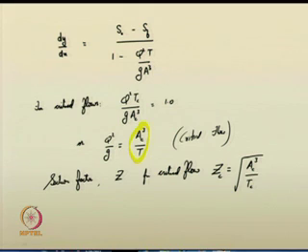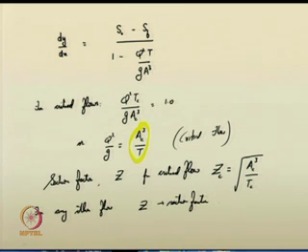So, for any other flow, not only critical flow, you can define the section factor. This is nothing but equal to the cube of area by top width, the whole thing you have to square root it. It is Z is equal to root of A cube by T. Like this one can define that.